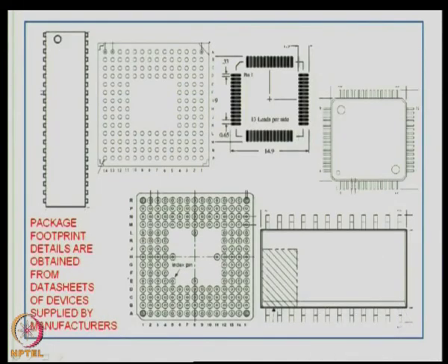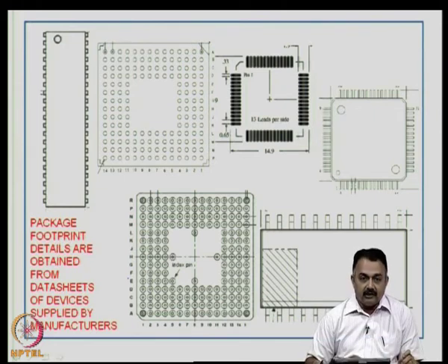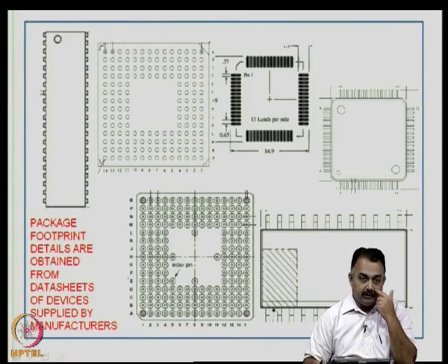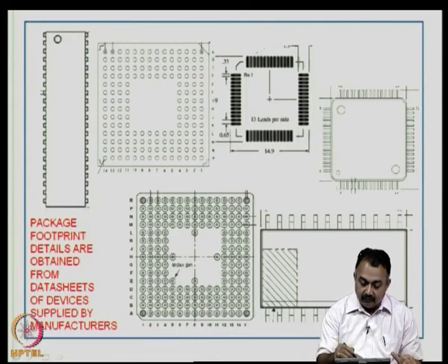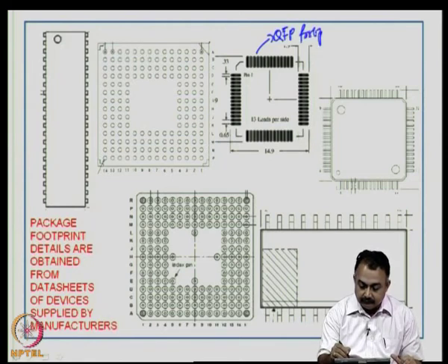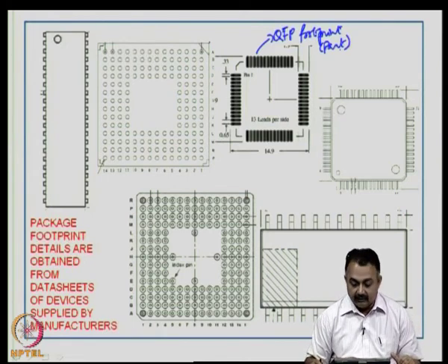This is an overall view of various mechanical details that you will see in your data sheet and which need to be well interpreted and invoked for utilizing the current footprint. For example, this is a QFP footprint or part, you can call it a part, that is available in any CAD package.